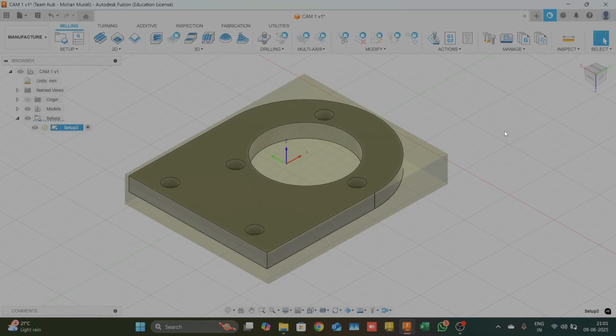So in this step, we have reoriented the X, Y, and Z axis to be in the right direction that we need, and especially the Z axis. It needs to be pointing upwards, normal to the part. X axis, you can choose how you want it. Secondly, we have defined the raw material size, and we have given the setup a name of 1001.